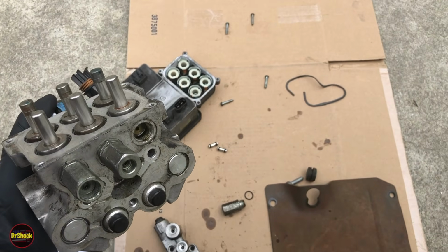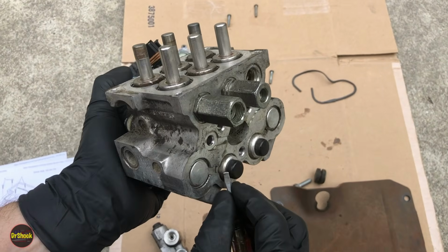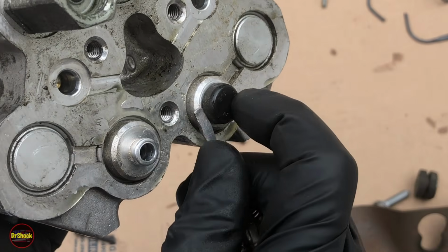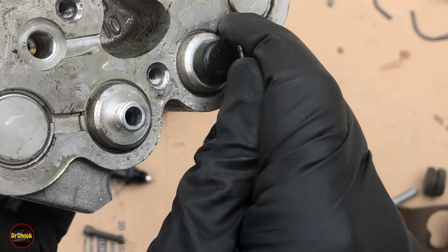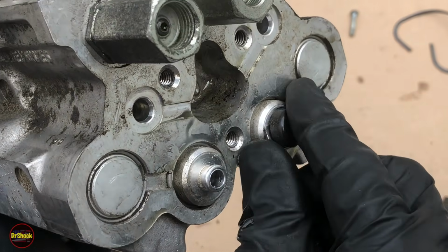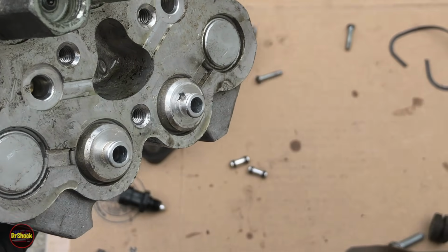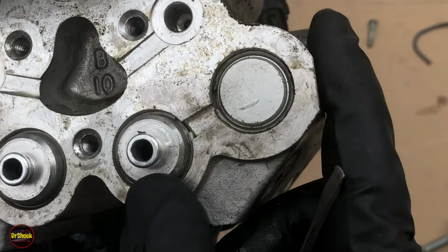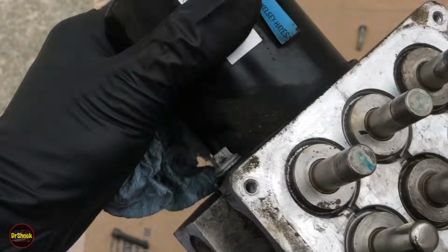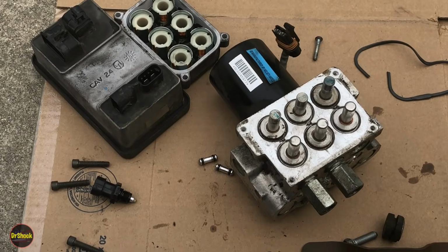Something else you want to take a look at is you can take a small flathead screwdriver and remove these dust caps. In fact, you want to make sure you've got these dust caps to prevent corrosion, particularly up in the salt belt states. This piece here is made of aluminum, so it's less likely to have that. I'll show you the ones on the combo valve. You just want to make sure you're not getting water running out of here. You should get brake fluid running out of there, if anything.